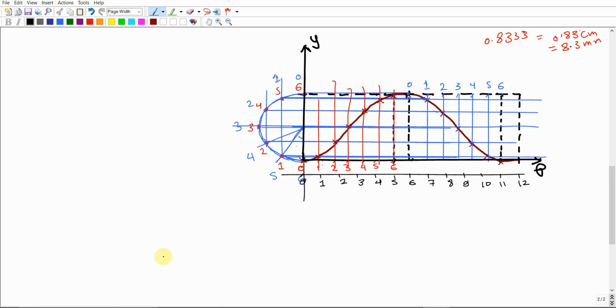This is gonna be the first axis over which the center point of rotation of the cam is going to be located, as long as we're working with an inline follower, and this is the type of mechanism that we are going to consider. An inline follower means that the axis of the follower motion is going to be considered vertically through the center of the cam rotation, as I'm going to show you.